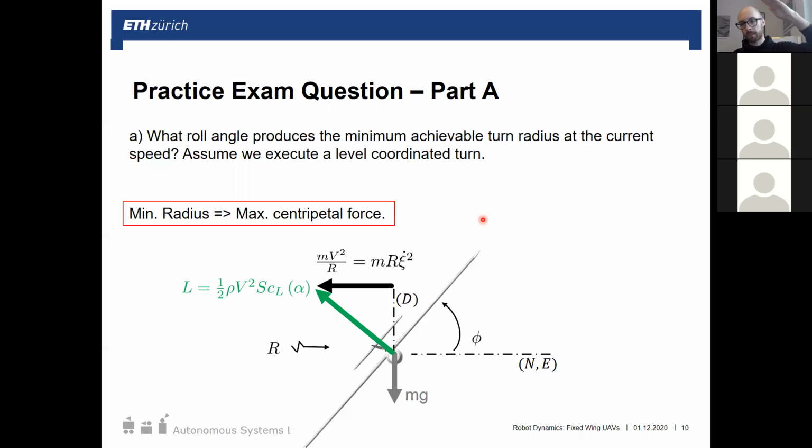We rotate through angle of attack and through slip to get to this wind frame axis. But I put a big red note in the slides because it's important not to confuse this with inertially defined wind. The wind frame is still within the air mass; it's not considering our inertially defined wind.